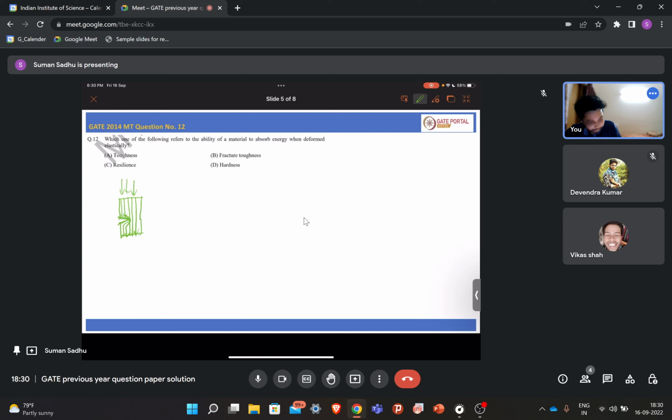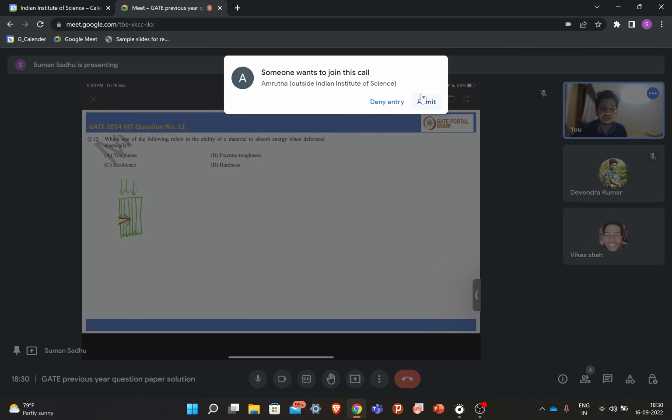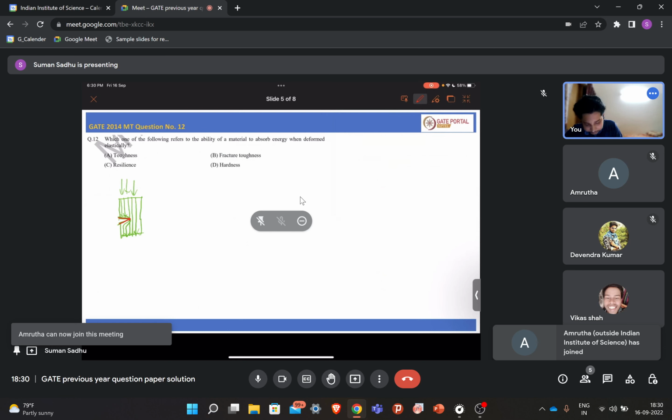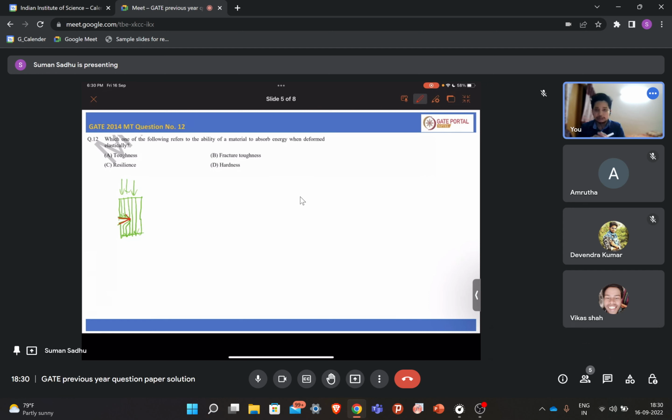So what will happen then near this crack? This is your crack, right? Near the tip, the stress intensity will be very high. So when you have a very sharp crack, at that time the stress concentration will be very high. If you think of it like the flow of water, near this thing it will bend, and more lines will pass through this sharp tip region.